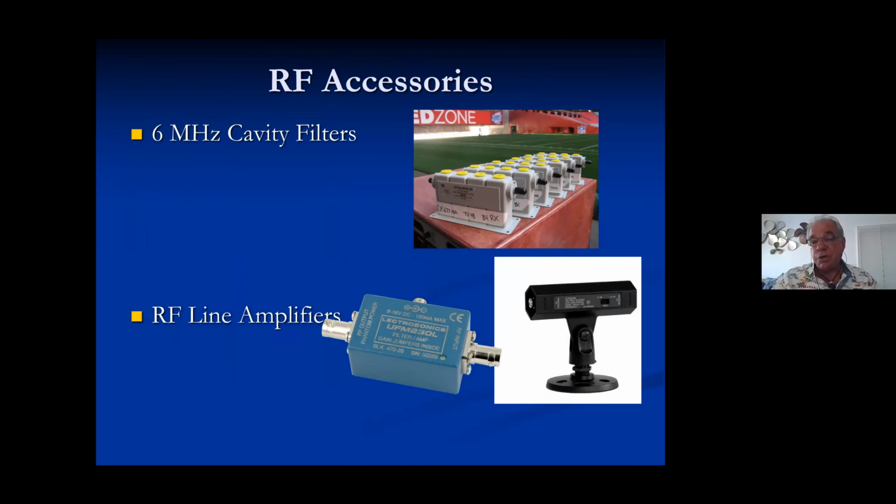An RF amplifier should only go in one place, and that is between the antenna. A filter should only go in one place, and that is between the antenna and the first active device. So the filter is going to get the antenna fed to it, and it will feed the amplifier. That amplifier from Shure goes from 470 meg to 950 meg. But you only care about 500 to 600 meg. So you're going to put a 500 to 600 meg filter in there so that Shure amp is not amplifying DC to daylight and picking up stuff that you really don't care about.